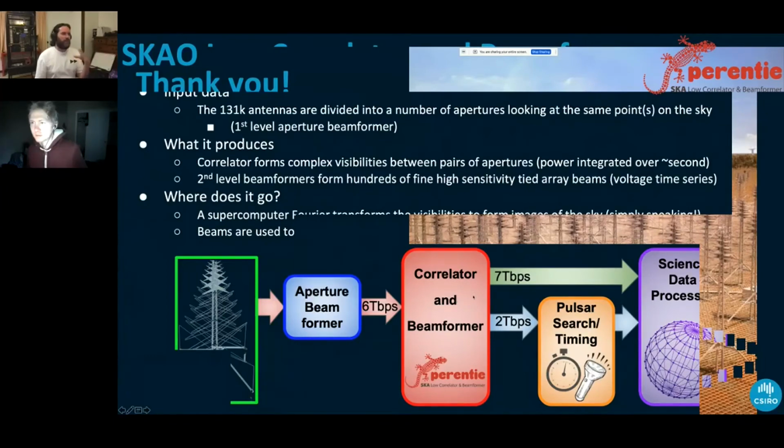The challenge is not, for the SKA, so much the bandwidth. For other projects, we've got another project called CryoPath. In this project, the P4 switch is receiving 28 times 99.5 gigs per second, and we need to send that to 32 Alveo cards. So in this case, we're pushing the switch to the limit, clearly.